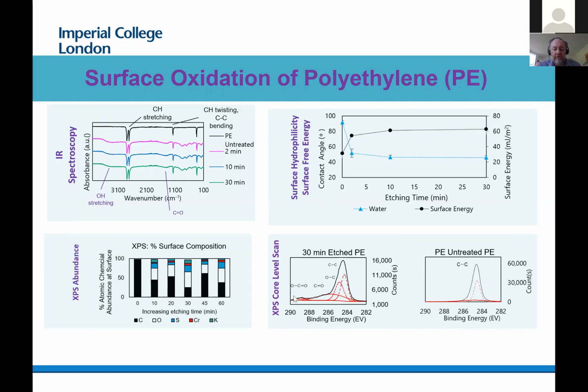So we've got some evidence here for carbon connecting to oxygen, carbon double bonding to oxygen, and also carbon bonding to oxygen twice. And that's important for forming carboxylic acid groups. So there's evidence that the oxygen groups are now chemically formed on the surface of my hydrocarbon. Basically, I look like I've changed the surface chemistry of my material.